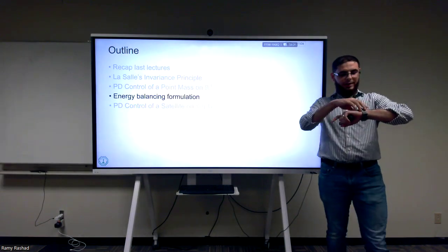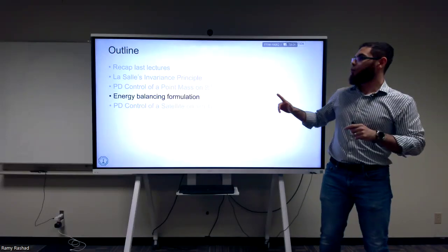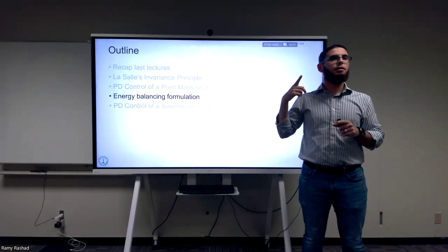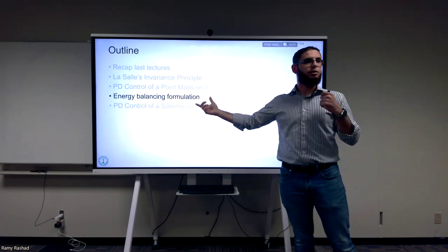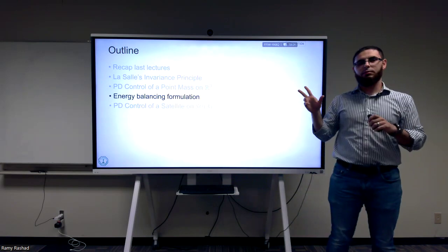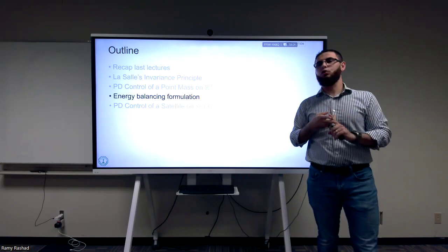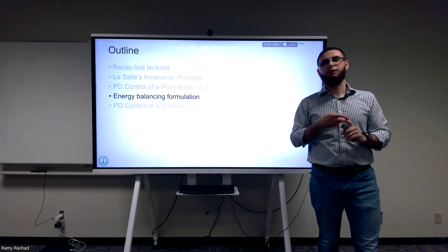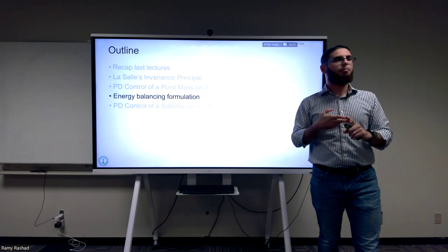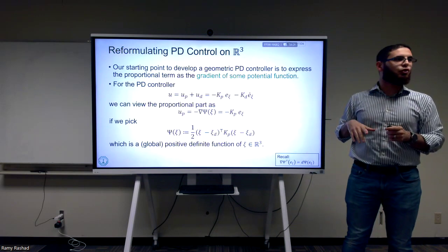The first, how do we extend the PD controller to the manifold case? We're going to reinterpret the PD controller as what it does to energy. Who here heard before, or knows, that a PD controller is nothing else than, I can reinterpret it as, the gradient of some potential function and damping? Good. Okay. So let's reformulate PD control on R3.